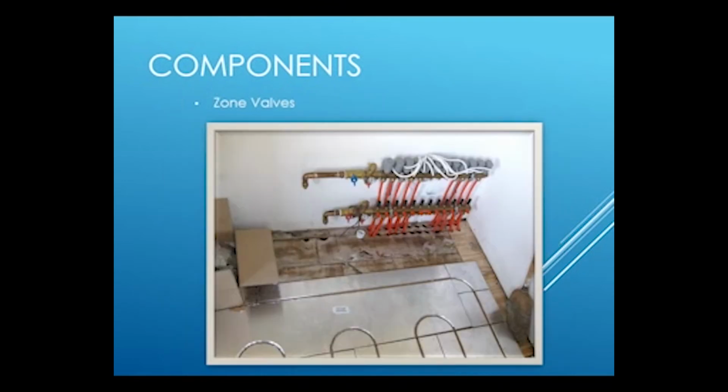Outside the boiler unit, we have zone valves, which are 24-volt hot water valves that are controlled by the thermostat. Some valves have an end-of-line switch to sequence other equipment. These are called auxiliary contacts, and typically we use these for the burner control. When we interlock the burner control, we can turn on the burners only when there is a call for heat. There are many different configurations depending on what the application is, and we can combine these with circulation pumps.